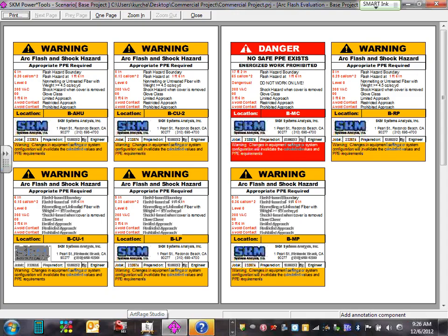This is what you're going to give to your electricians. Can you guys see the only one that's dangerous to work on? It's the meter center. Remember that meter center, work on it energized, there is no circuit breaker ahead of it. Everything else, the red means you cannot work on this equipment energized. Big deal. Cool. And then you can hit print and print them colored.